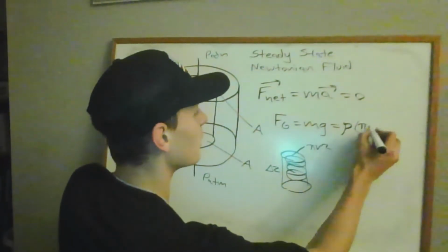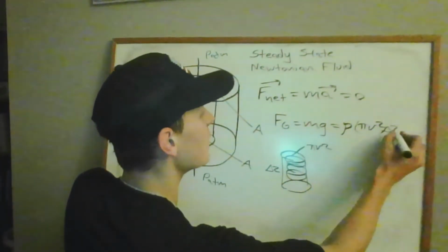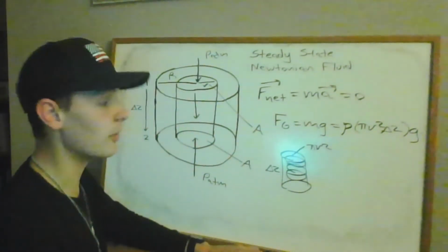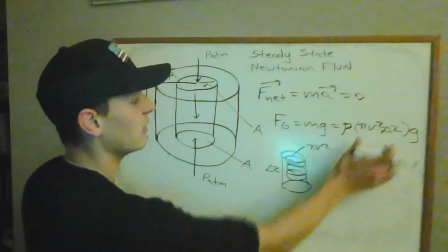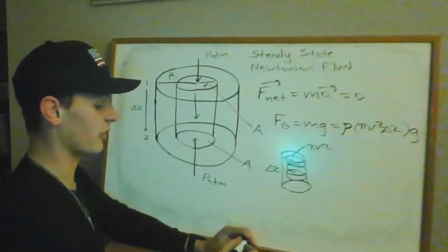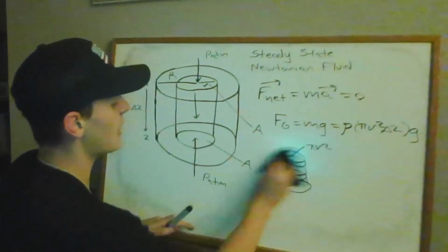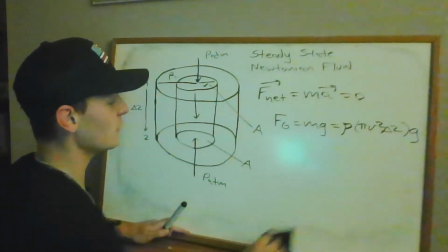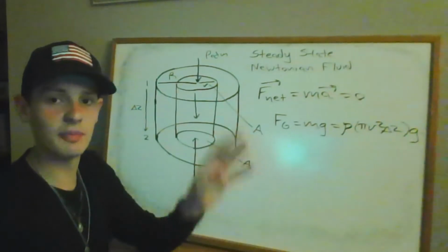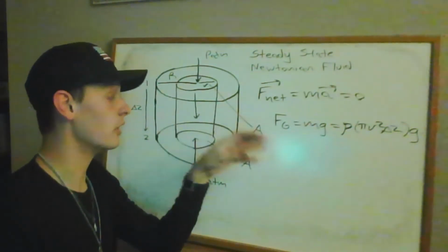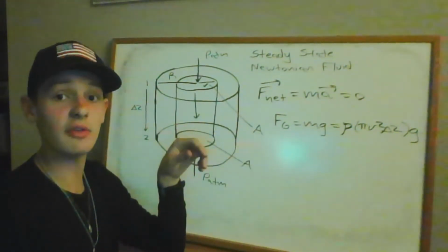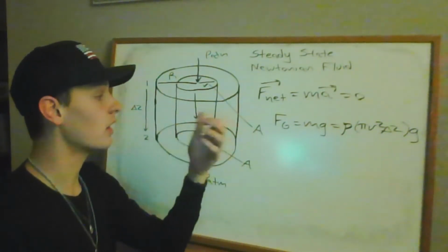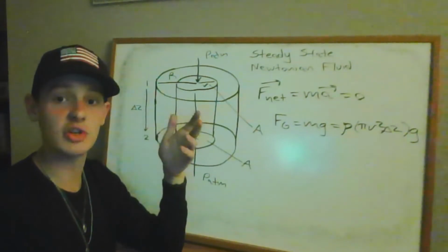That we need to put here, okay, because we're trying to account for the weight, which is the volume multiplied by the density. Okay, hopefully that's visible on the end there. It looks like it is. Okay, so that's your volume. Then, of course, don't forget the acceleration due to gravity. Now, there is another force that we have to consider here. You would have to ask yourself, based on what I revealed before getting to this expression for the gravitational force on our controlled volume, where or from where does the frictional heating emanate?